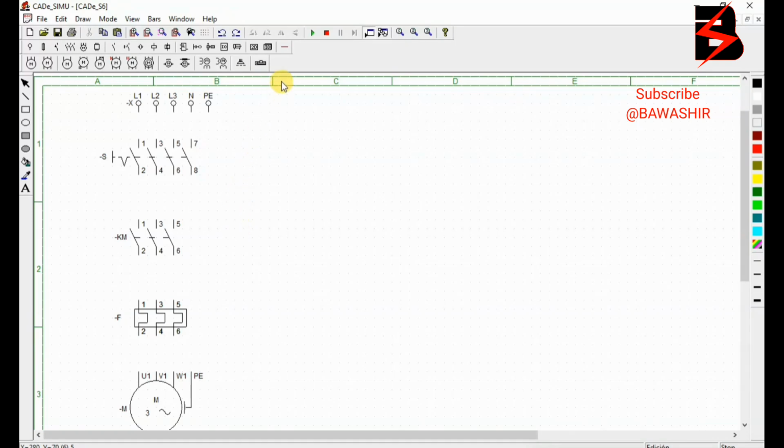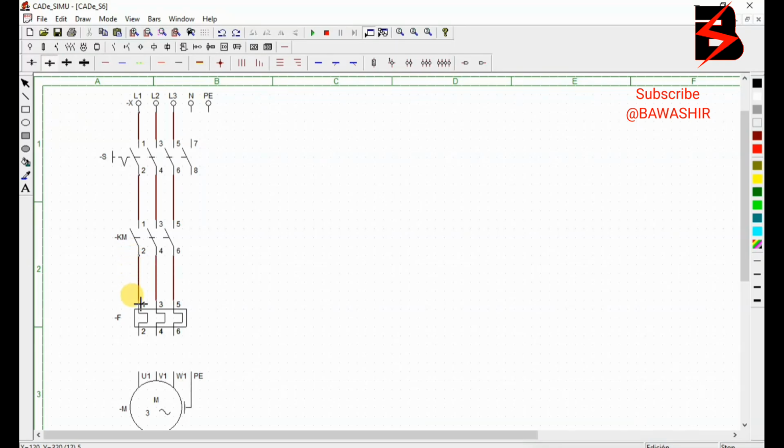So now let's try to do the wiring. I have here my cabling. Shall get cable routes. Shall connect from the breaker to the contactor, then from the contactor to the overload, then from the overload to the motor. So in simple terms, we have line 1, we just connect through all the components up to the motor, and line 2 and line 3. So for the neutral, I'm still on a 3-line connection. Let me choose